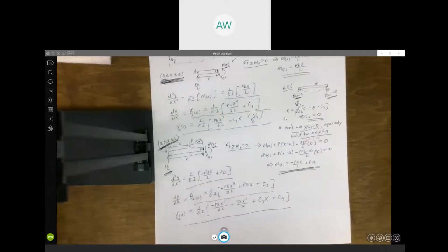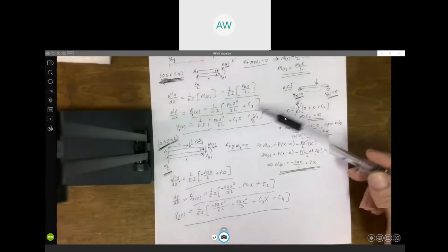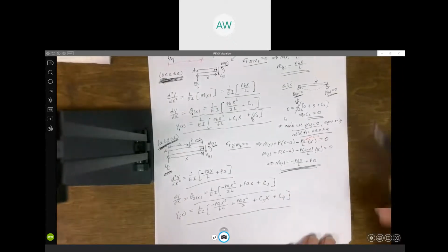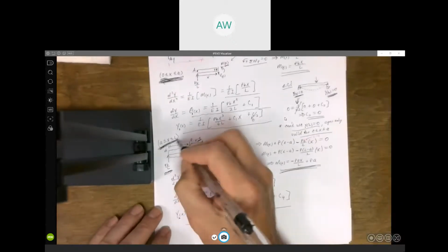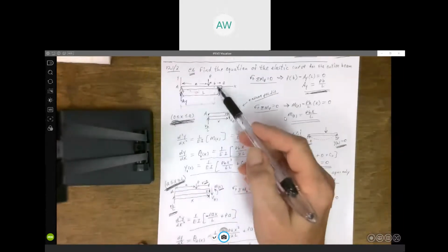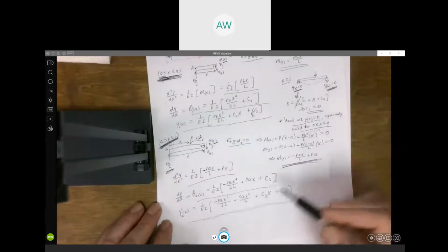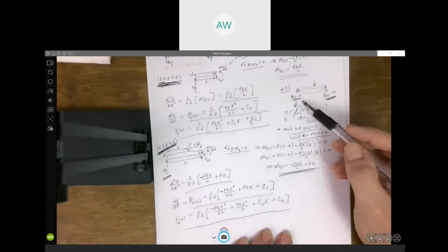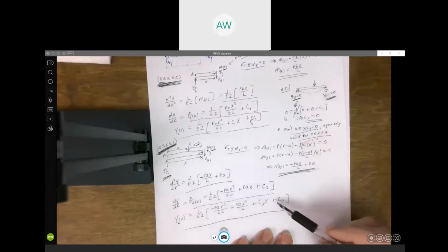All right, well, we went from having one unknown constant, right? We didn't know what C1 was up here. Now I got two more. Well, now here's where we can use this boundary condition, right? Because remember, these equations we got here are valid for this part of the beam, right? For x equals L, I can apply this boundary condition to these equations. I cannot apply this one, the fact that the displacement is 0 when x is 0. I can't use that down here, right?